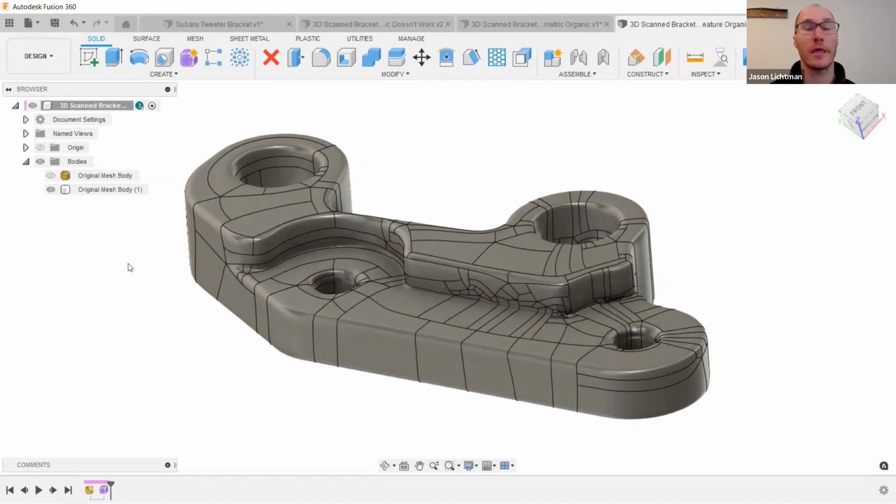There are advantages of that. But the base feature option, I think, is really helpful because it allows you to manipulate the shape itself if you'd like to. And most importantly, it allows you to fix any conversion problems. That parametric conversion is either going to succeed or it's going to fail, whereas the base feature version gives you opportunities to actually fix the problem itself. So that's a really good look at what this is doing.